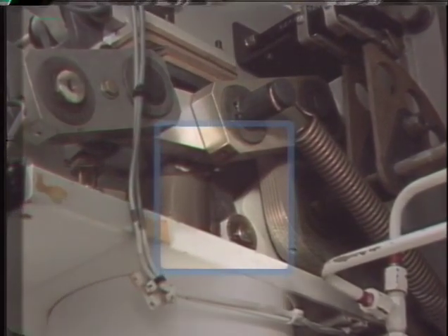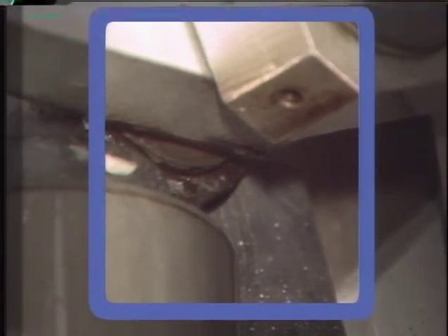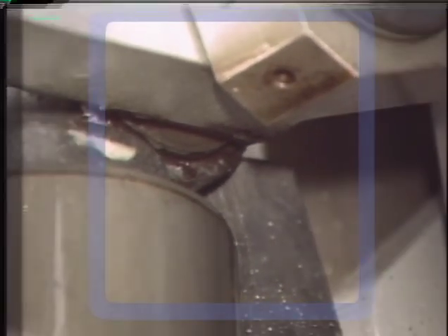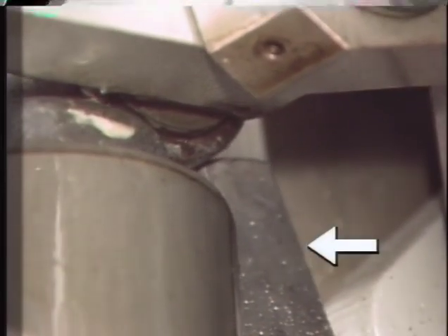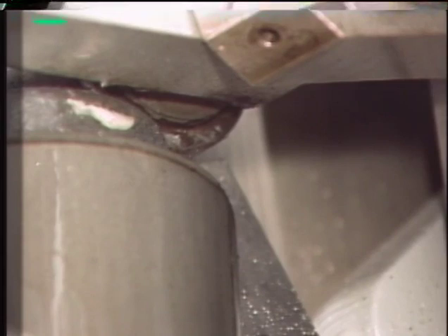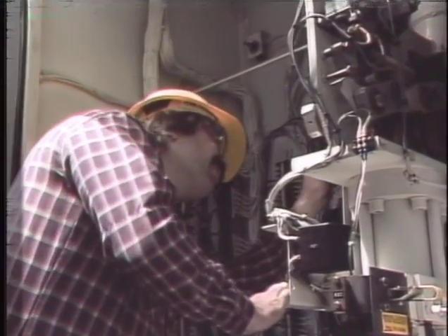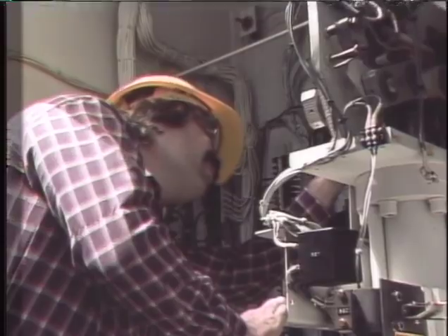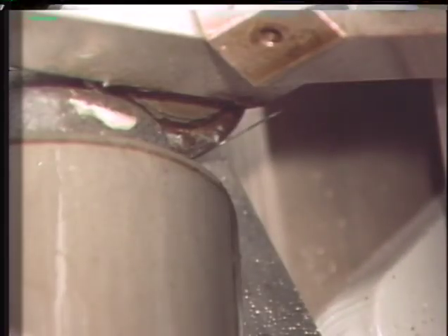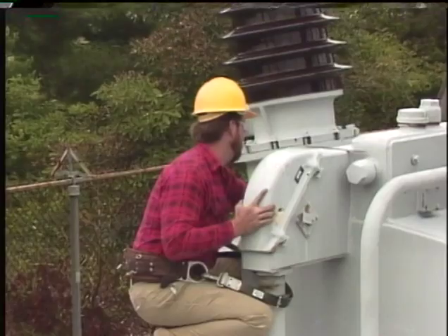Latch clearance is the amount of clearance needed for a latch to consistently drop into a given position. To check latch clearance, start with the breaker open. Slowly close the mechanism so that the latch, such as a holding latch, drops in position to lock the mechanism in place. Crank the mechanism beyond the latch position as far as it'll go. Then measure the gap between the latch and the surface it normally rests on. The gap should fall within a range specified by the manufacturer or company requirements.